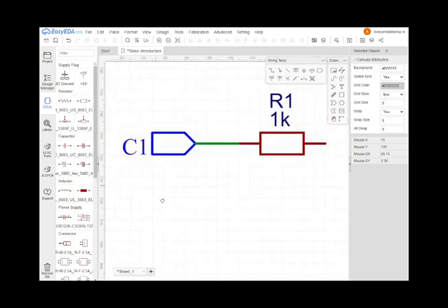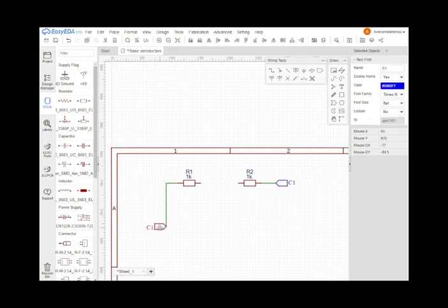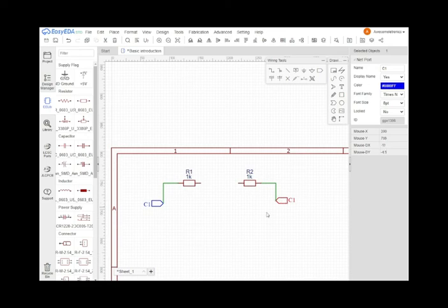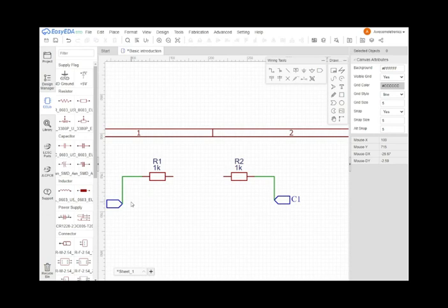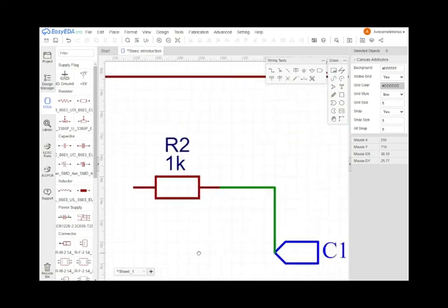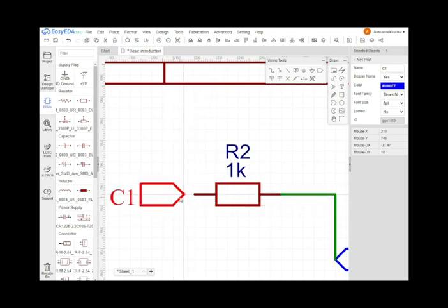And as you can see, here we have C1 and C1. The thing is, there is some invisible connection through these ports, alright. So that's why we use them, because it's very easy and not that messy. And here there is some invisible wiring that you cannot see. If two ports are named the same, there are invisible connections, and you can just copy and paste if your name is so long, or yeah, it's your choice.